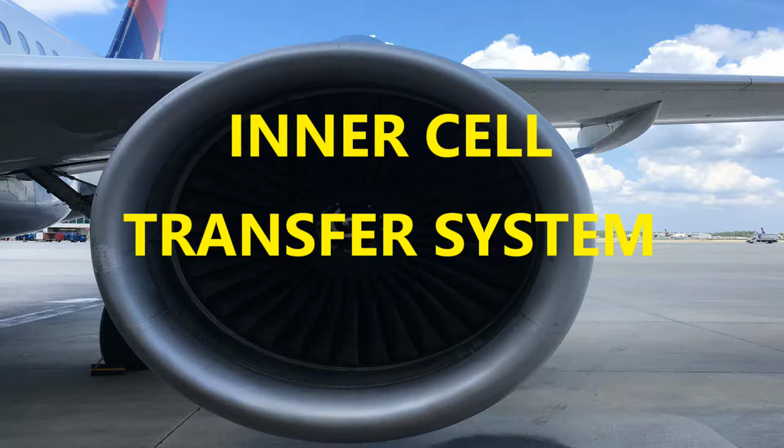You also have indication for this. This is going to be your ECAM SD fuel page. It's going to show a warning there. Of course, remember I said green is good. Well, green is the condition for this particular case. The vertical lines mean that the valves are closed. Okay, those intercell transfer valves are closed.